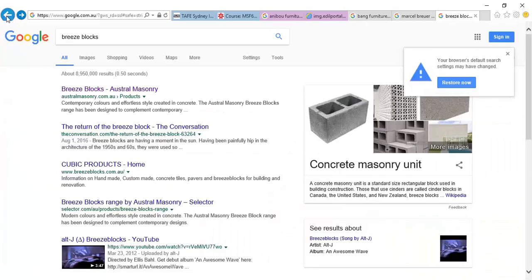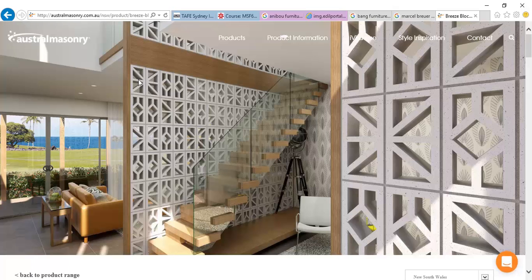By doing it this way, all I need to do is come back to this individual panel family and make a different pattern, and then it'll update every screen in the project. I might have 1,000 of them, but I just need to edit one little thing, and it'll propagate through the whole project. So I really like that.